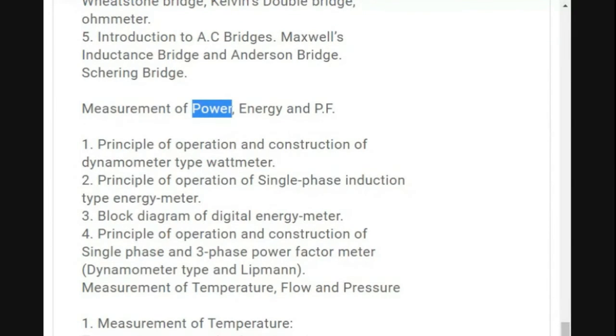So accordingly this wattmeter has two components effectiveness, or we can say that this instrument is working as per the two parameters, that is voltage and current. So one coil which is supplied with the voltage value, what does that mean, that coil is connected in parallel. Okay, and whereas if it is in series, then that coil is in series, then we can say that it's a current component. So I hope till here everyone is able to understand.